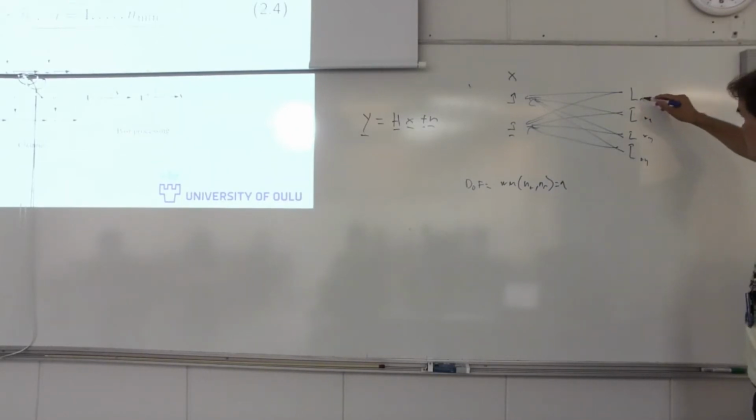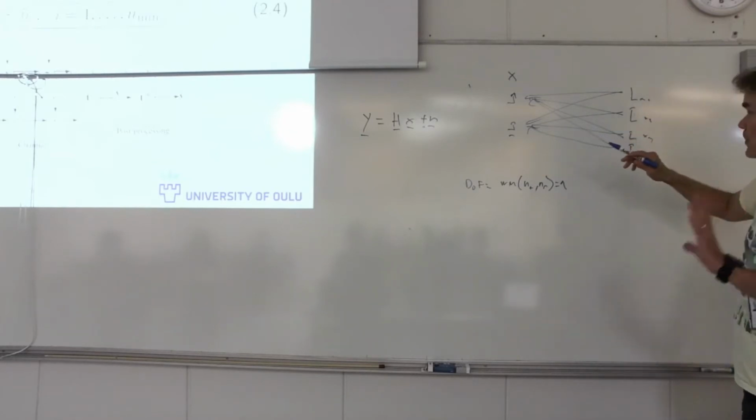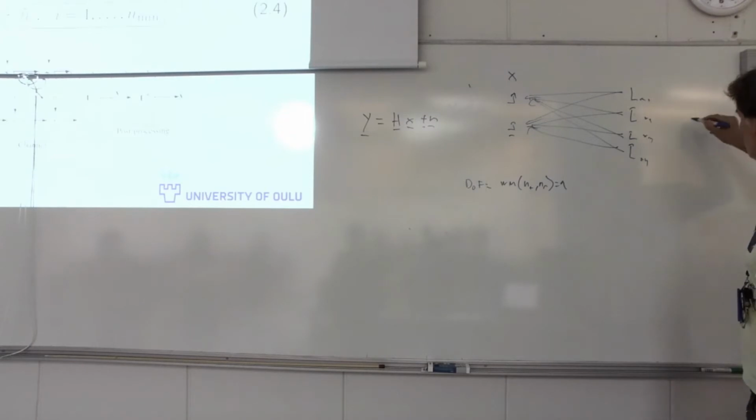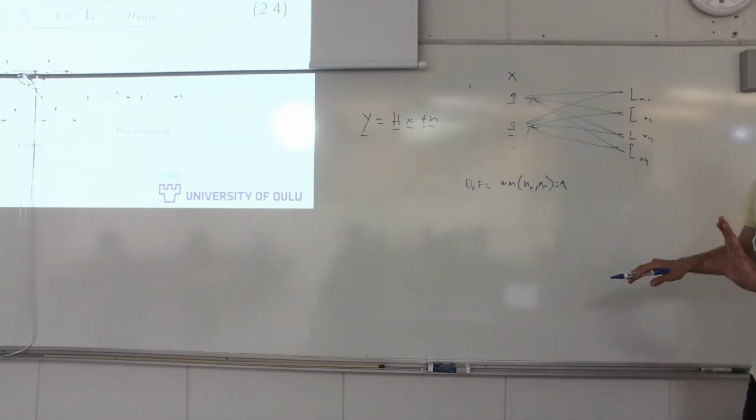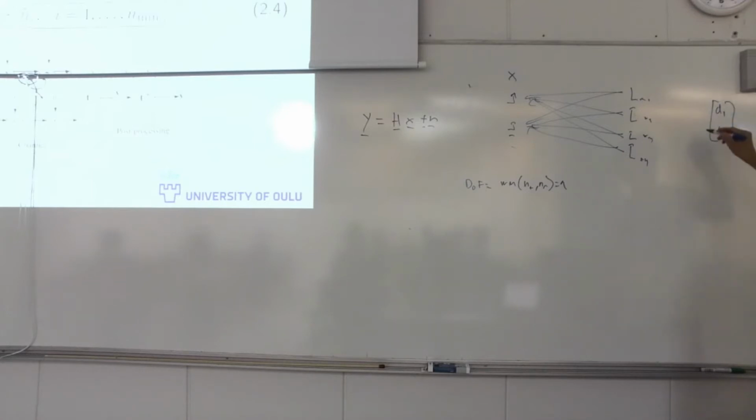We can perform so-called beamforming or precoding. Instead of sending 4 streams, we know by default that we shouldn't transmit more than 2 streams. So we generate a vector of 2 data symbols, then pass that through a power loading, and then through a precoding matrix.